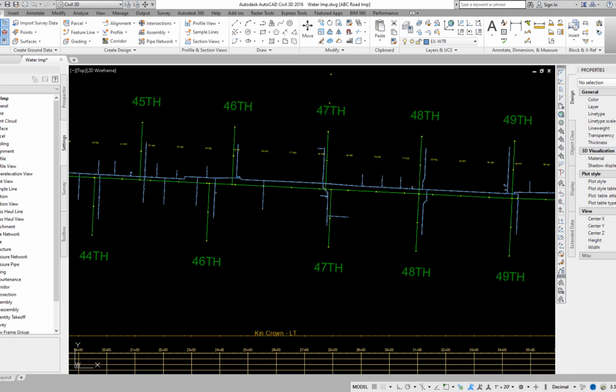The profile of the water line should be designed to eliminate crests or high spots, especially on larger diameter pipe, as much as possible. The crests create air pockets, which are troublesome in a water system because they have higher pressure losses than other sections of the water line, can be a potential location for creating water hammer, and can cause problems in pressure testing the water line. Air release valves are generally installed at crests to eliminate air pockets in the water line.